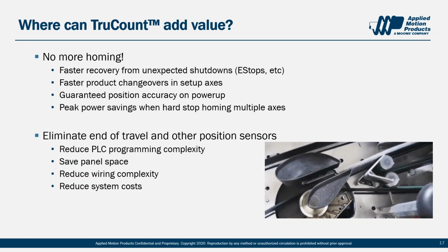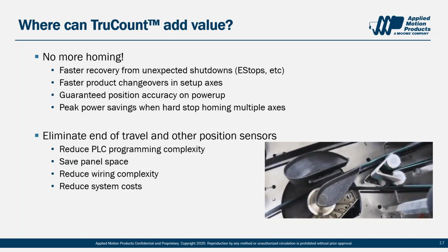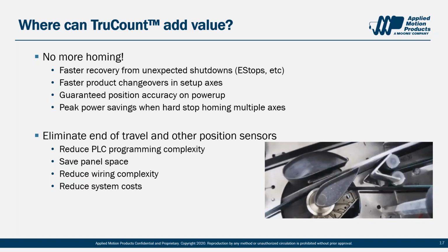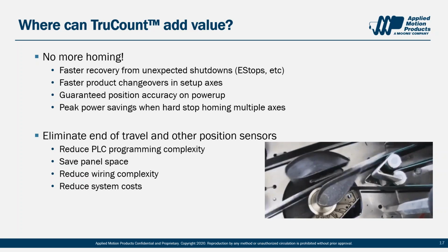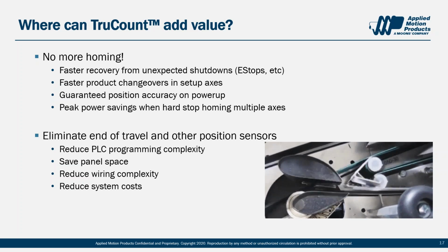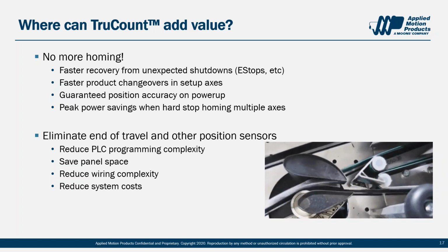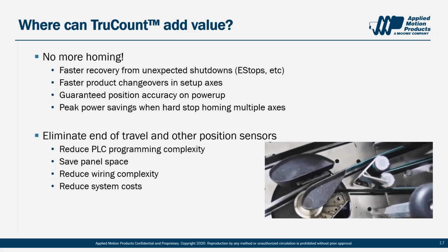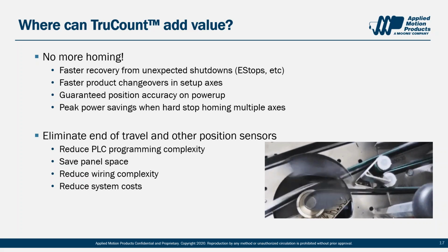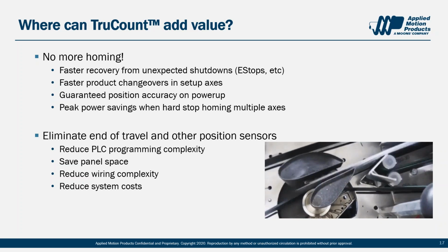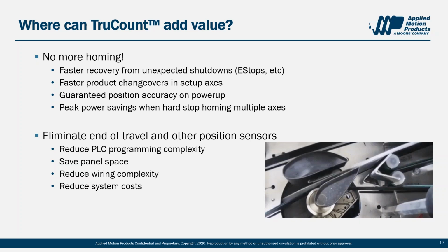Looking at their power budget, they realized that even though the motors individually were small power consumers, this hard stop homing period was driving their peak power consumption for the entire machine. The first idea was to space out the homing sequences to run more sequential smaller groups, but the startup time of doing that in series was rejected out of hand. Switching to absolute encoders was able to eliminate that homing sequence completely, which achieved the desired result of pulling down their peak power demand for their machine.